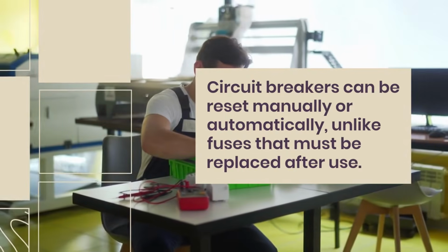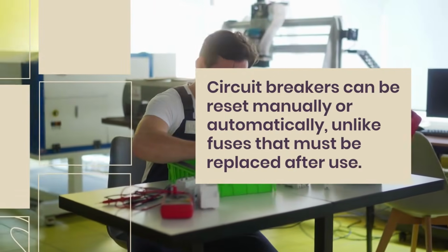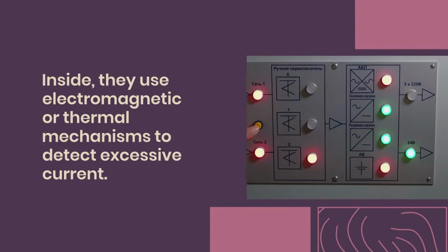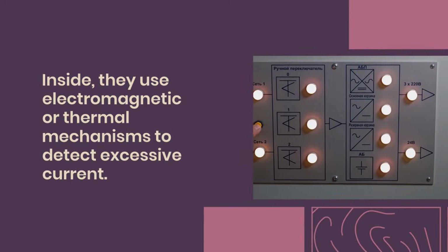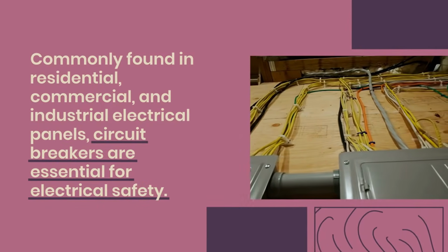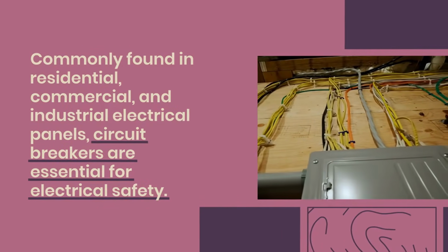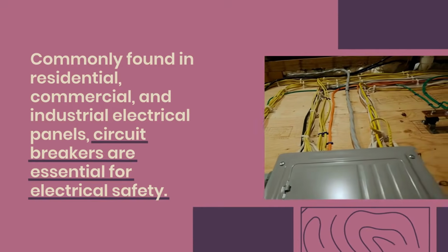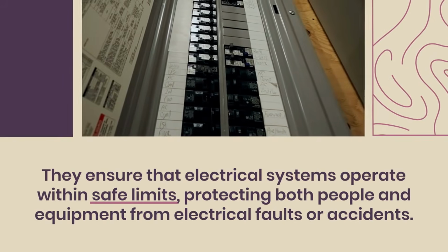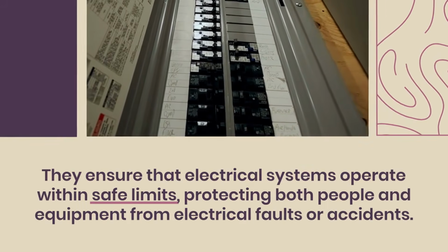Circuit breakers can be reset manually or automatically, unlike fuses that must be replaced after use. Inside, they use electromagnetic or thermal mechanisms to detect excessive current. Commonly found in residential, commercial, and industrial electrical panels, circuit breakers are essential for electrical safety. They ensure that electrical systems operate within safe limits, protecting both people and equipment from electrical faults or accidents.